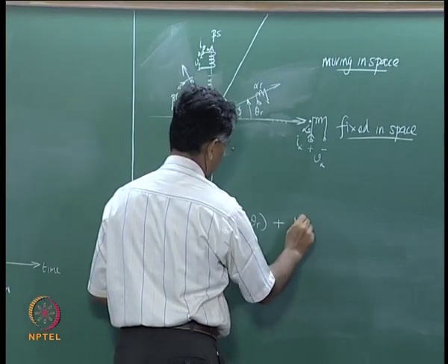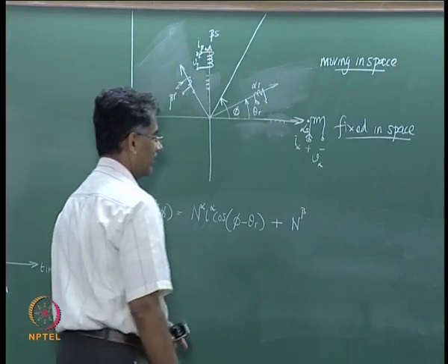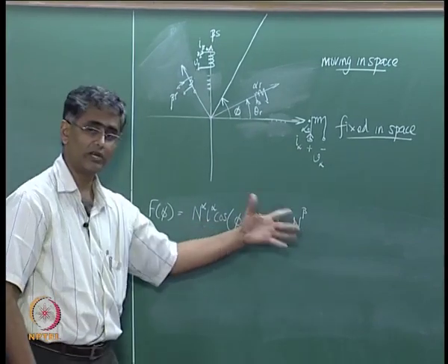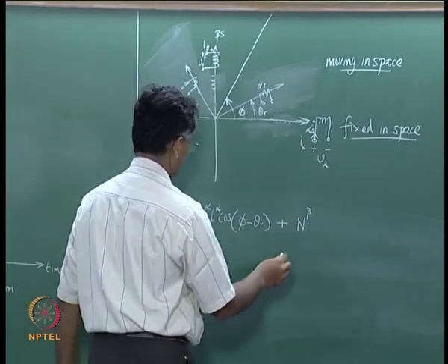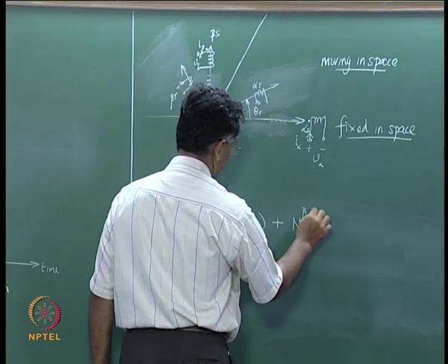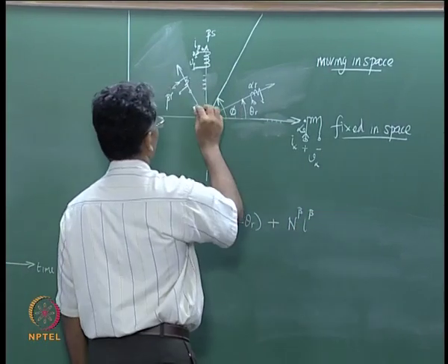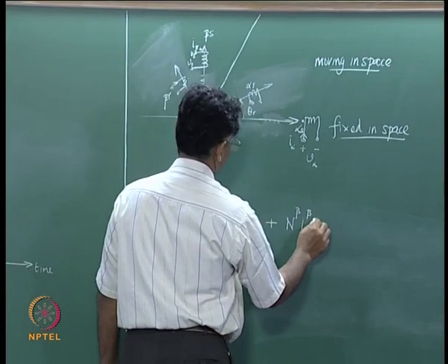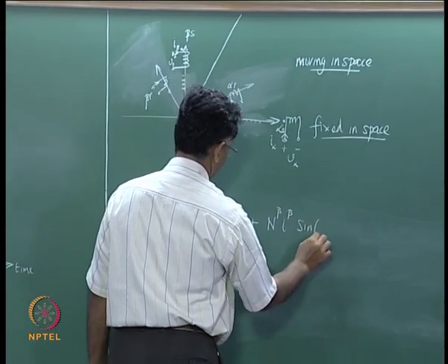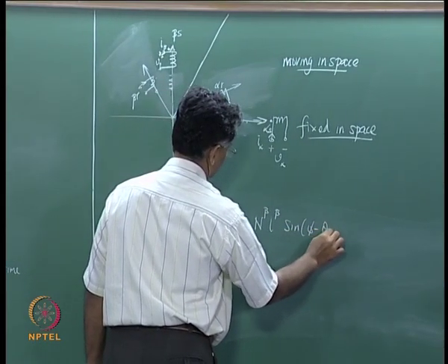So that again is n beta, and we know that n alpha and n beta are the same, so let us have that in mind, then multiplied by I beta multiplied by sine of phi minus theta r.